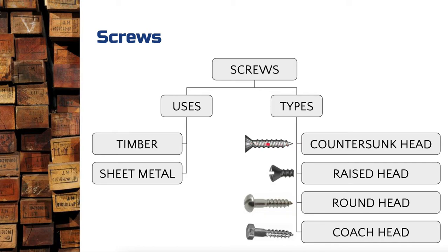Then the shank is the whole length there, okay, from tip all the way up to the top. The shank doesn't have to be completely covered in thread. The thread sometimes will only cover 3/4 of it, and that's totally fine as well. And it will depend on the application that you're looking for. But wherever the thread goes to is where your gripping power is. The rest of it, there's no actual gripping power. It's just part of the screw. So that's a bit of an overview of what the screw looks like. That's the countersunk, most common one that we use.